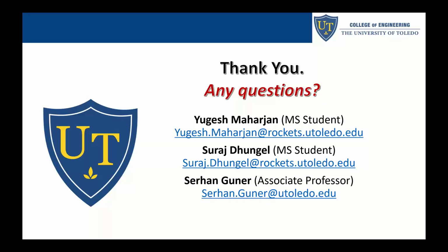On top of that, you are going to be getting tons of output because BRR is not just for simply supported beams, but it's for continuous beams. Your box beam is pretty much simply supported in many cases. Because you are using BRR, you're going to be hit with pages of output, and it would be very difficult to analyze and understand. If you take a box beam bridge and analyze it with AdBox as well as BRR, you will see that you are going to be making tremendous effort, order of magnitude more effort to analyze it with BRR.